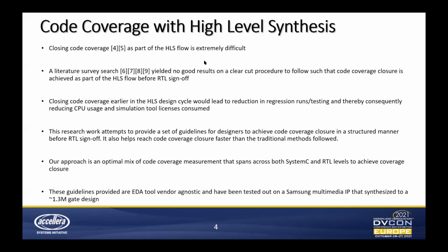Our research work attempts to provide a set of guidelines for designers to achieve code coverage closure in a structured manner before RTL sign-off. It also helps reach code coverage closure faster than the traditional methods followed. Right now, I think people do most of the HLS code coverage at the RTL level, so that's something that we have tried to improve upon.